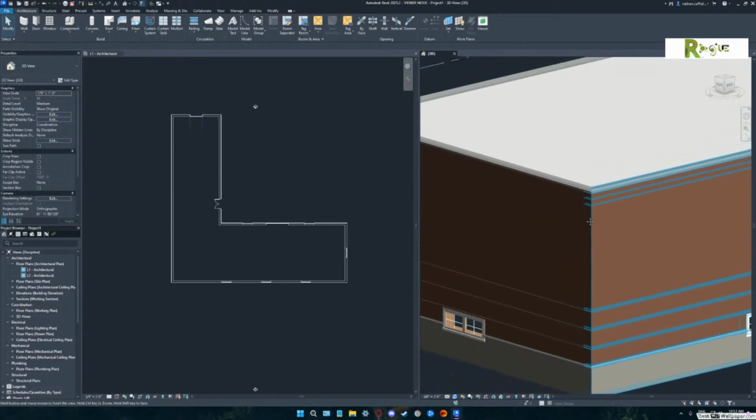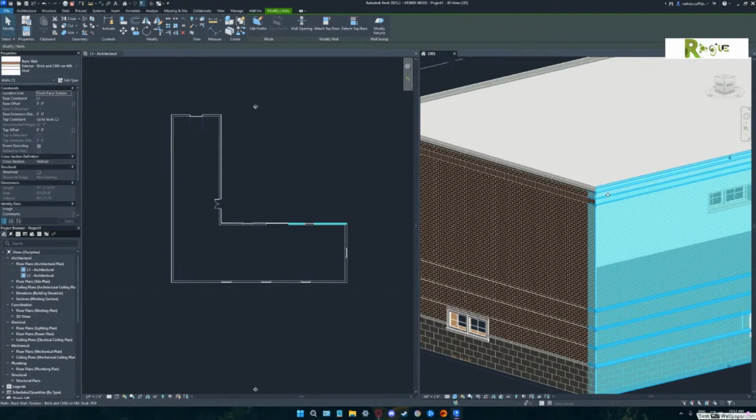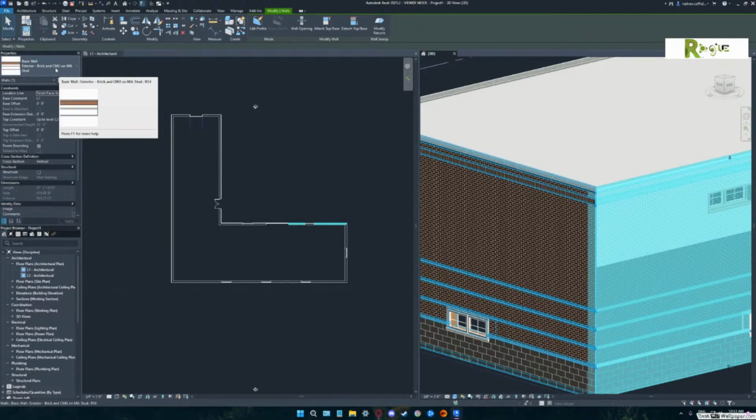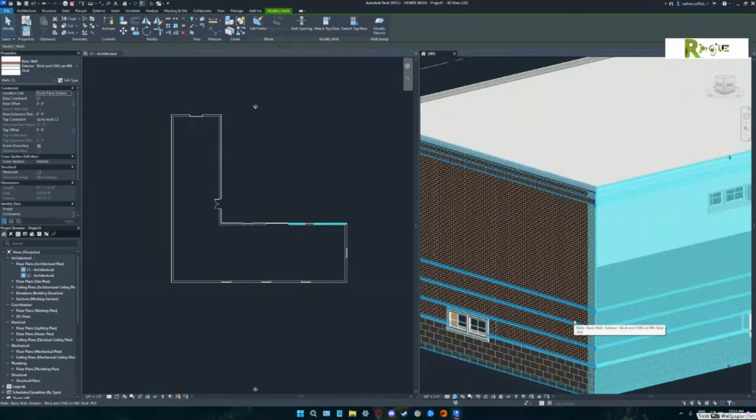You see the wall type that you put in is this pretty special wall type. If you pick the wall. Okay. This type wall, which is in the template, has sweeps built into it. Okay. That's a good way to go sometimes, but sometimes like those bands that you're seeing at the bottom, they don't go all the way around. You only have that on the front of the building. So I typically don't like to build my sweeps into the walls. But I'm going to show you where those sweeps are.